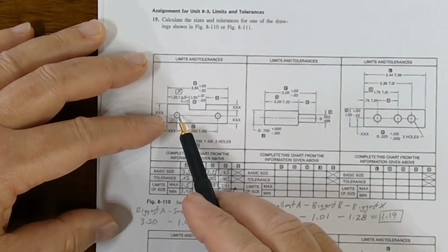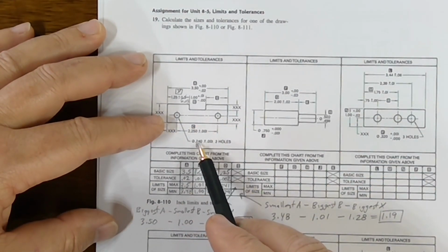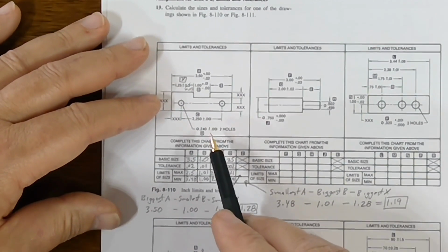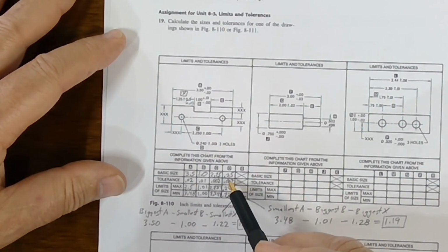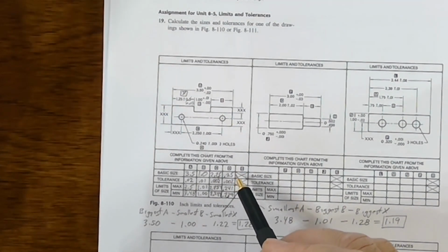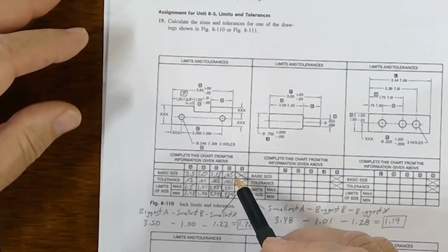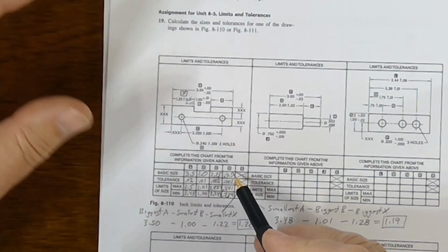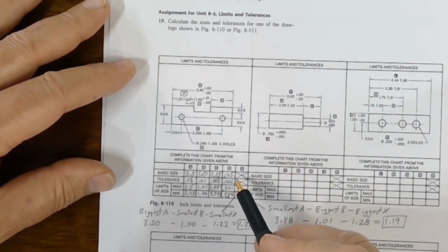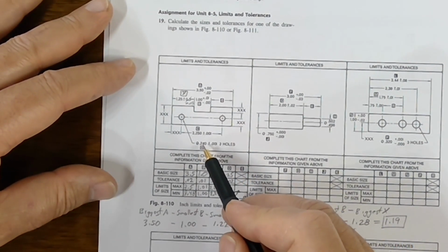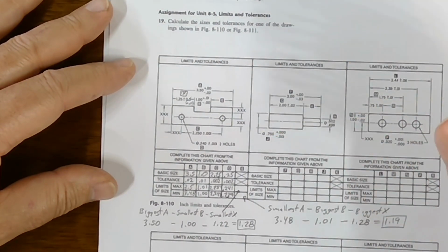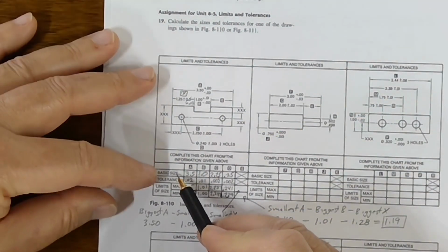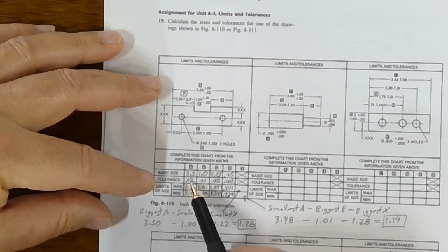D, this is a hole. So they're giving you 0.24, but just round that to a 1/4 inch. So say 0.25 for the basic size, because in the inch unit system, we typically go by 1/4 inches, eighth inches, half inches, things like that. We don't really use 0.24 to talk about stuff. Like if it was a bolt, you would just say a 1/4 inch bolt, but it's not actually a 1/4 inch. So that's the basic size. All right. Then figure out these tolerances.